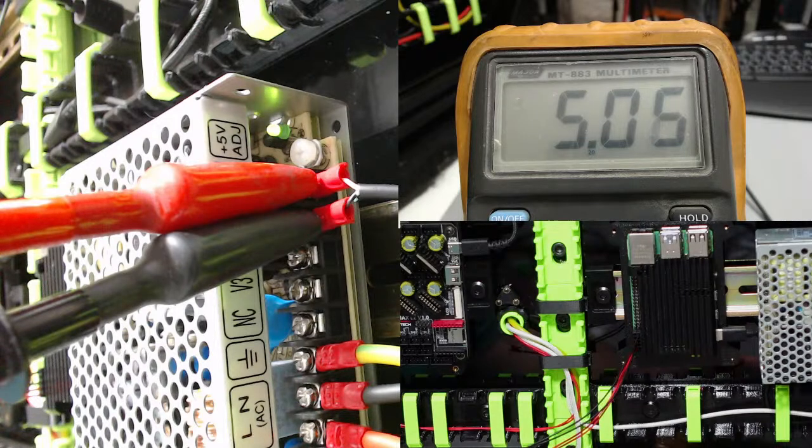But a Raspberry Pi 4 has a bit of a problem in the sense that it doesn't like voltages under 5.1 really. It works, but every now and again you get under-voltage alerts. So the best thing for us to do is to actually check the voltage on the Raspberry Pi and make sure that we're giving the Raspberry Pi enough voltage. And in wanting to do that, the first thing I want to do is show you the difference between measuring the voltage at the power supply and measuring the voltage at the Raspberry Pi.